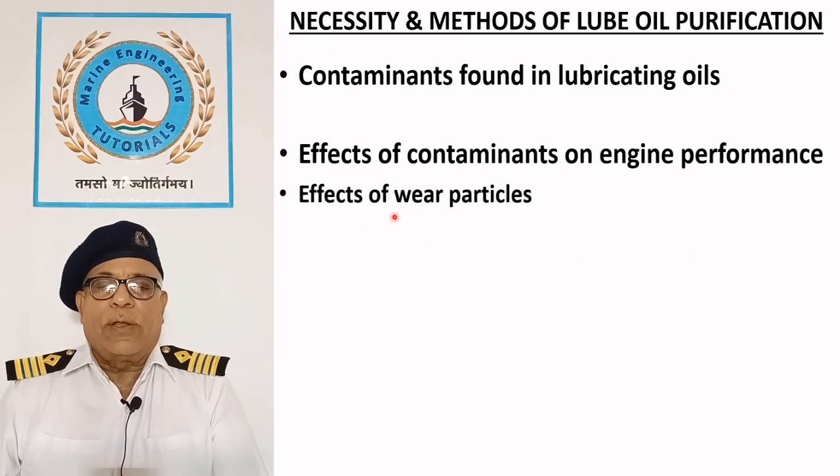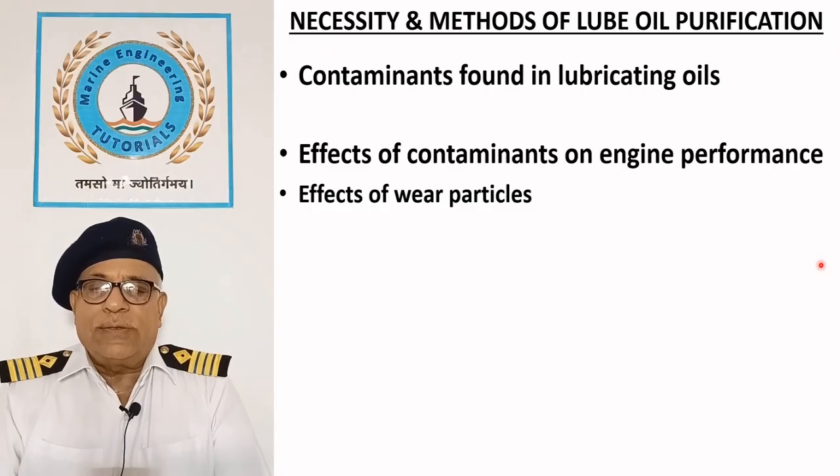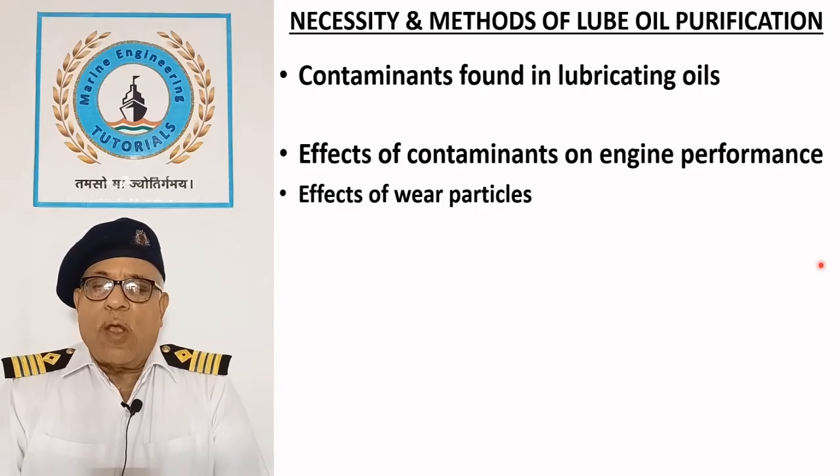Effects of wear particles. Wear particles can clog filters and oil passages, disrupt hydrodynamic oil film, and result in metal to metal contact, causing localized heating, micro seizures, and surface fatigue. They act as catalysts to promote further wear and cause damage to bearing surfaces, crankshaft journals, piston ring, and liner surfaces.